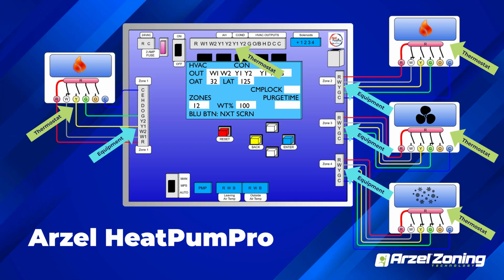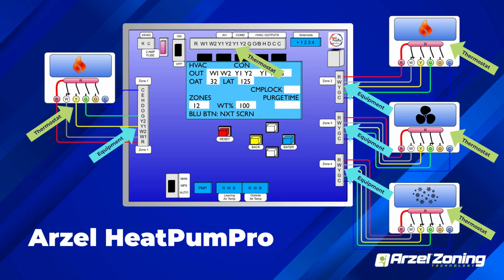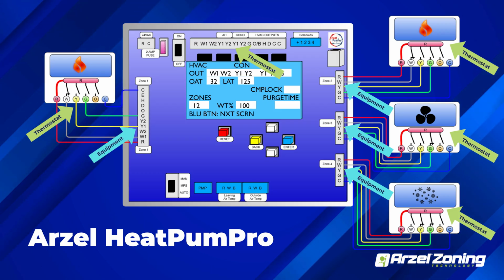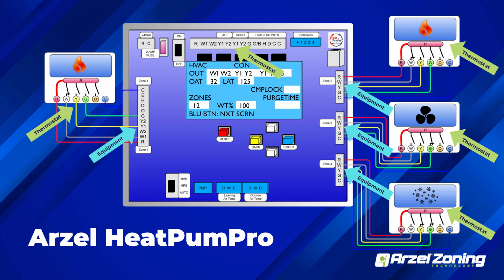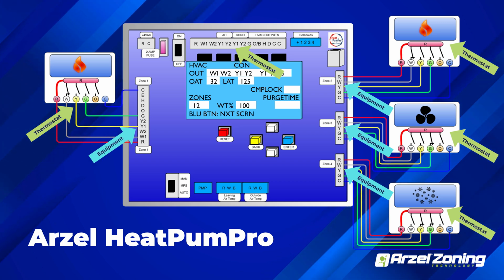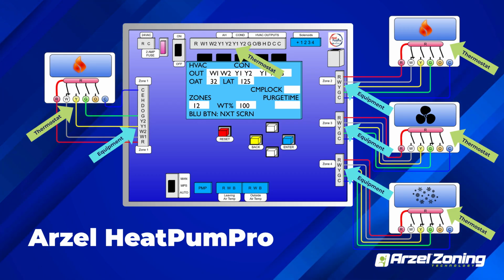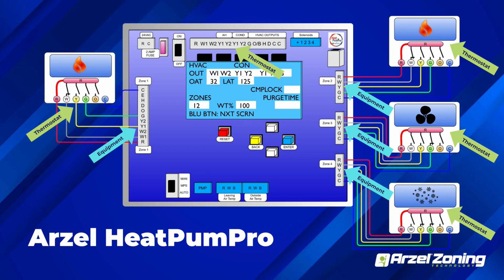So your furnace has all its safety switches. The HeatPumPro and the AirBoss do have a high temperature and a low temperature protection built into them. So that's where we look at that line that says out. If it is listed on that output line, it is energized going to your furnace. We look at it where it says zones. That tells us exactly what zones are being serviced. If we don't see our thermostat calling listed in the zone box, that thermostat's not receiving its call.